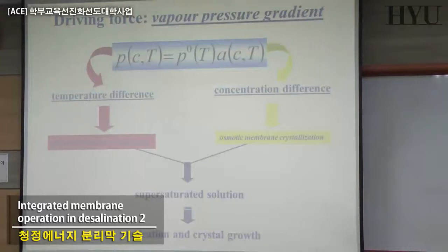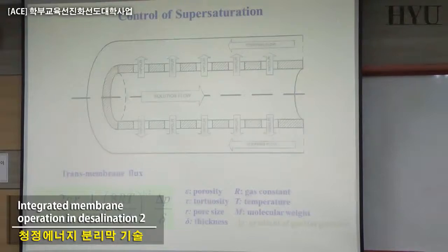And the story, as we mentioned already, is that we have to create a supersaturated solution and induce nucleation and crystal growth. I just want to show that this is the reason for which we can have a much better uniform distribution. Because in the normal crystallizer, stirred, etc., it's very difficult to control the homogeneity of the solution. Here, in the membrane system, each pore is a crystallizer.